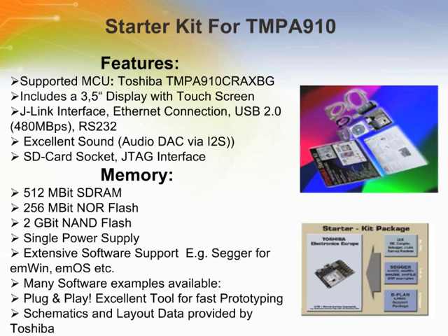This slide gives you information about the starter kit used for the ARM controller, TMPA910. It has all the enhanced features like J-Link, touchscreen, sound audio DAC via I2S, SD card socket, and it also has a 512 megabit SDRAM, 256 megabit NOR flash, and 2 gigabyte NAND flash.